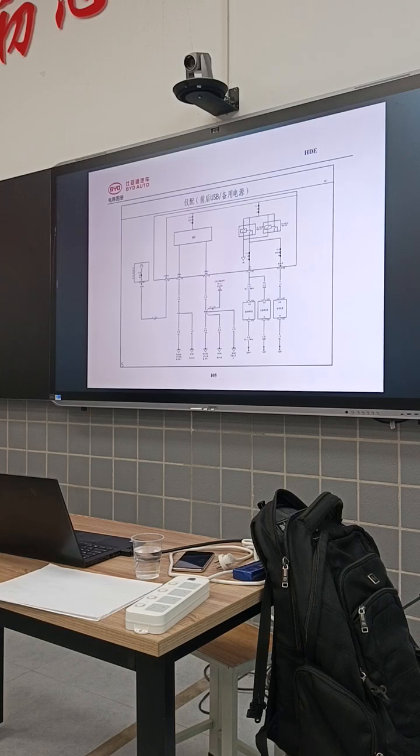But what we do, we look at what is similar to what we have, then we can use that. We also have OBD testing equipment. So we use that one, the translated version, to check. Because sometimes the diagram might not be available. If it's a brand new car, the diagram is there. You just go straight to the diagram and open the book.